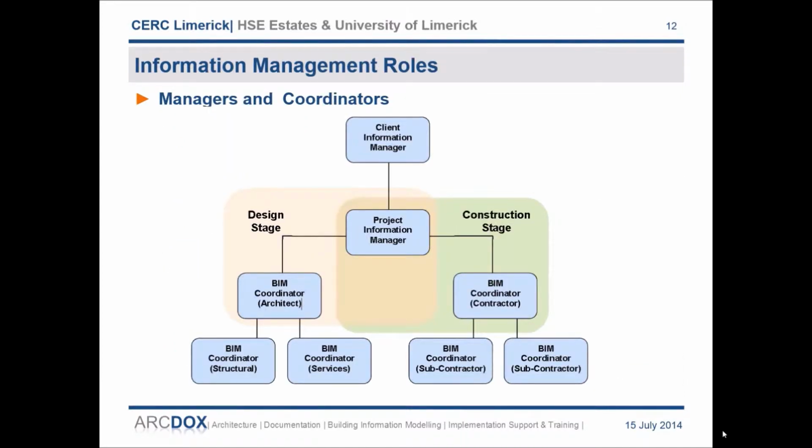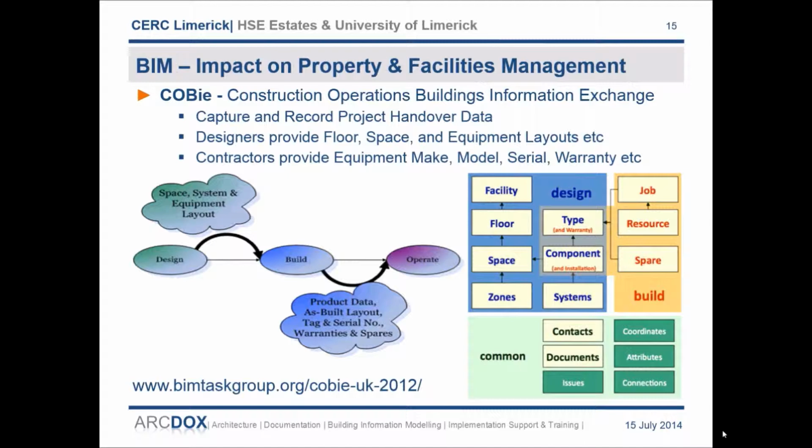An appointed project information manager will coordinate the efforts and contributions of all parties, as set out in the scope. The specification requires all designers, contractors and subcontractors involved in the project to submit at key stages the asset information required by facilities management for post-construction operations in an agreed, structured digital format. As a minimum standard, COBie, Construction Operations Building Information Exchange format, has been specified in the UK using Uniclass 2 classification. This will ensure that the data is well ordered and ready to be imported into the operations systems without requiring the facilities managers to retype the information. This is set out in the specification for the digital safety file that is cross-referenced to the BIM data.